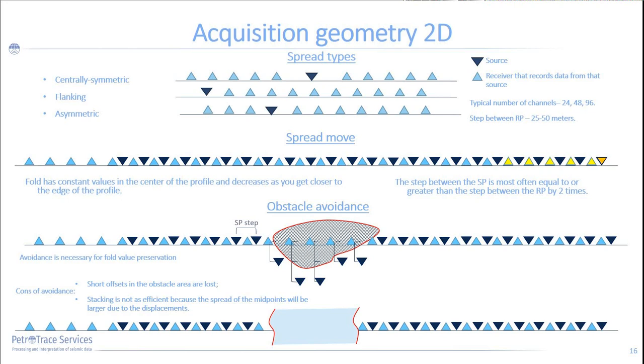Therefore, often those shots and receivers that had to be skipped are placed and shot before and after the restricted areas, by increasing the pitch of the shots and receivers there. As a result, the number of bases per CMP point is maintained or reduced within tolerance. This, of course, does not completely replace the regular profile.